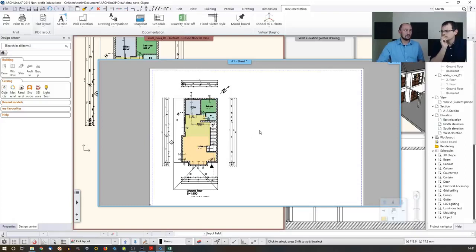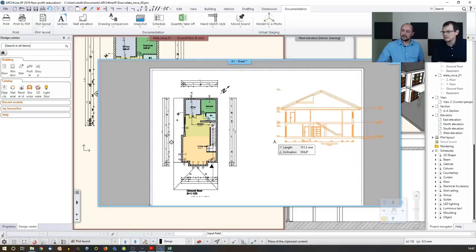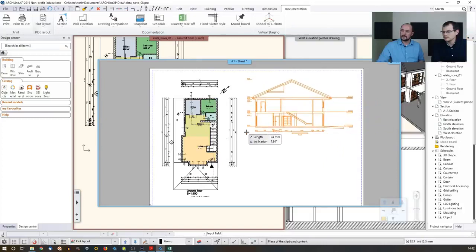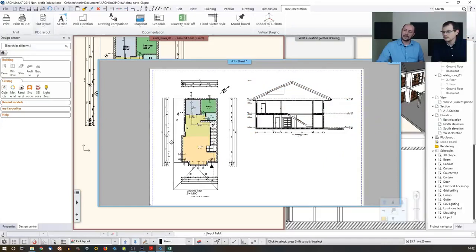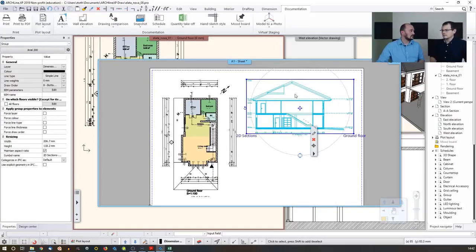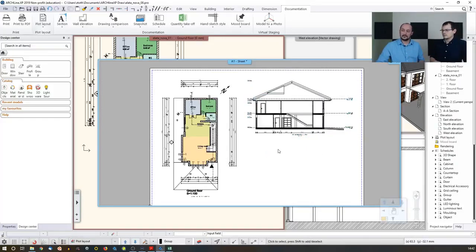We actually created a 2D section. So the 2D section, because it was a 2D view, it's appearing here. And it's the drawing itself was placed on the ground floor of that 2D drawing. So I just click and place and release. And I believe, again, 1:100 will be perfect. And let's just place it somewhere here nicely aligned. I align it, and when I like the position, I release. Again, this is something that I can select. I can trim it back if I don't want to see the whole content. And I can also rotate and move just as I would do with any other 2D content.